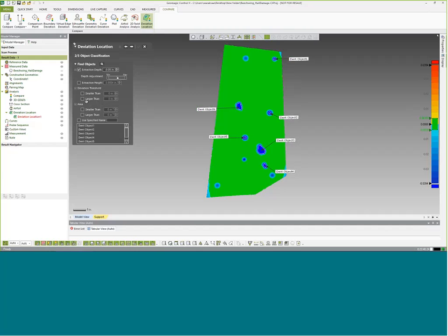I'm actually just going to use deviation threshold and say we're going to look at stuff that is of a certain depth overall. That's going to flag an item for us to investigate in person essentially. So let's do this, and I'm just going to make this like minus 0.1. So we'll do essentially a 1/8 inch here. So we can check that out.